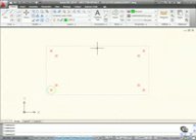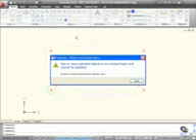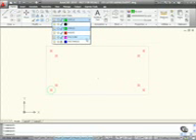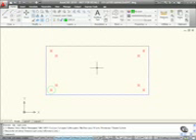It's locked now. So if I select it now, like so, and then try and change it onto a different layer, let's say the nodes layer, it won't let me. AutoCAD says it's on a locked layer and can't be updated. So how do I get out of that? How do I unlock it? Well, that's easy. Layer pull down or Layer Properties Manager, click on the padlock, and that then loses the locked status. Notice it comes back to the full color. So that's the first part of your layer management.